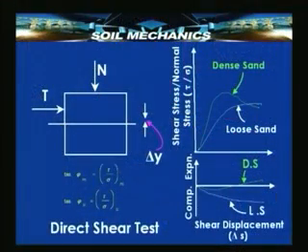Here is a look at shear strength from the point of view of the type of soil. If you have a cohesionless soil subjected to a direct shear test, this is the kind of relationship you will get between shear stress and shear displacement. If it is a dense soil, it will undergo a little bit of compression and then expansion. If it is a loose sand, it will undergo compression continuously.